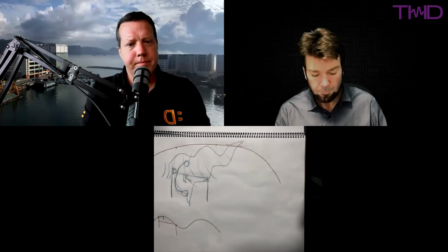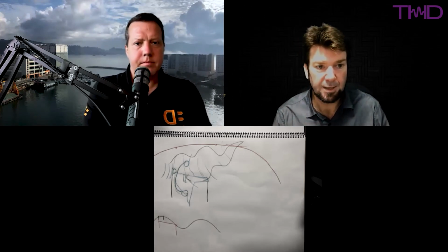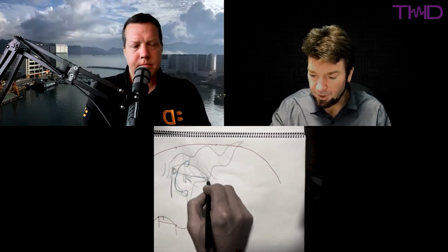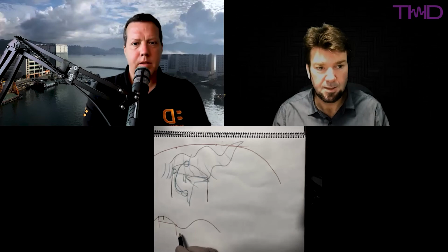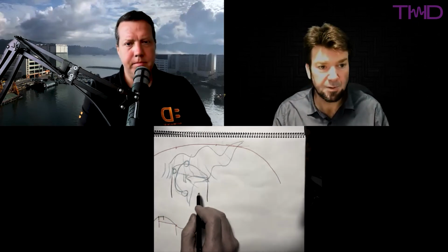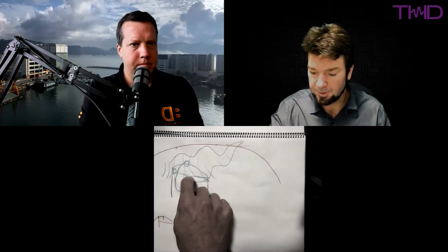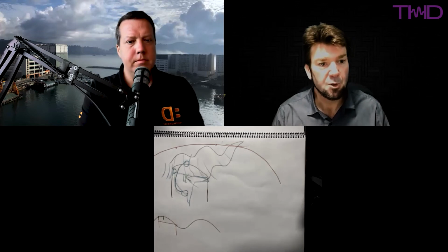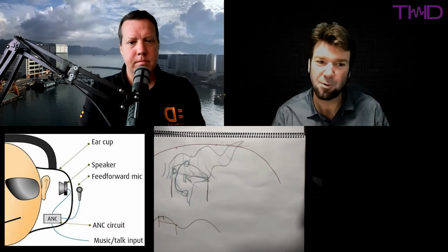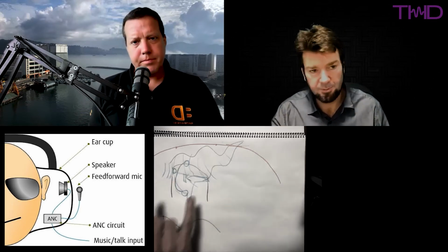Okay. So for feedforward, you're trying to match a response from microphone to ear canal and driver to ear canal. And in fact, you just calculate a filter directly from that. There's no instability problem because there's no connection between those two. You may add noise rather than subtracting it, but you won't have instability. So you're trying to match this transfer function.